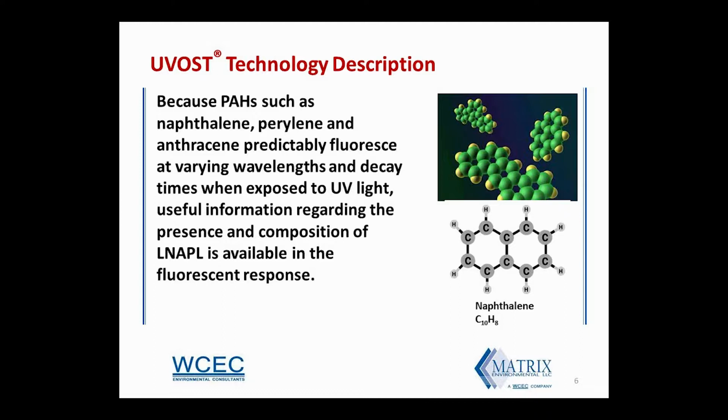Because some of the lower molecular weight PAHs, such as naphthalene, are highly fluorescent, diesel is one of the ideal LNAPL materials to be identified with the UVOST. But I'd also like to mention that monoaromatic compounds like pure benzene or xylene do not fluoresce efficiently, so LIF will not reliably detect LNAPLs composed of these materials alone.